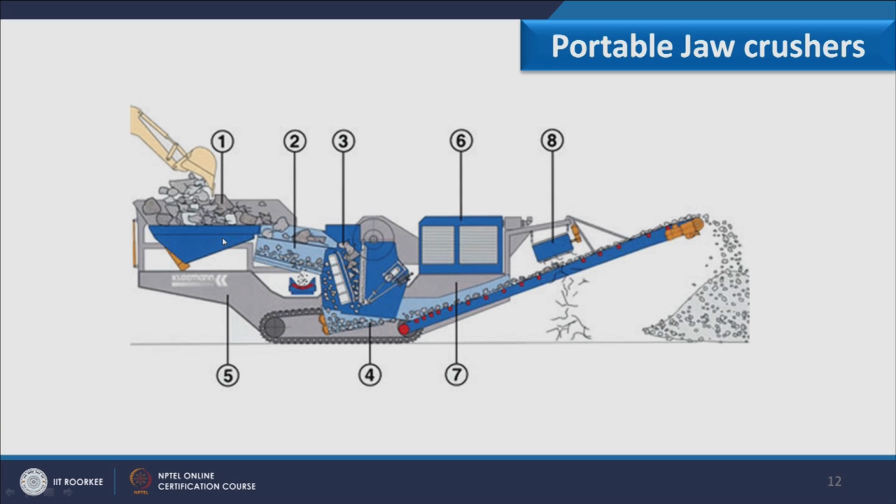So, this uncrushed rock can be passed through. Yes, that is the drawback of the jaw crusher. Sometimes what happens when material is not compressed properly, it can pass through the crusher uncrushed, or if we have not decided the size of the gap between the jaws properly, then uncrushed rock can also be passed through this.